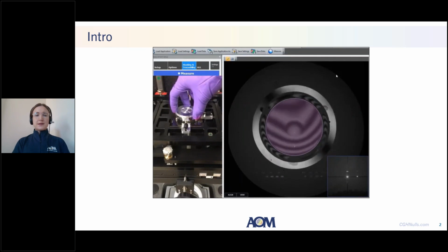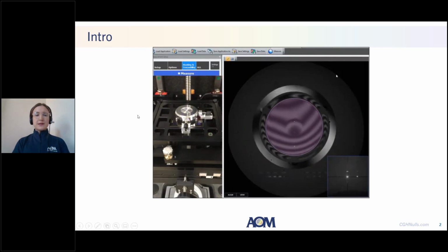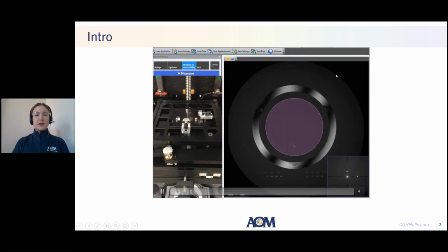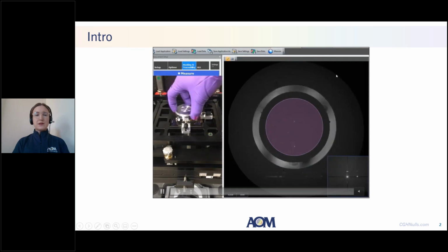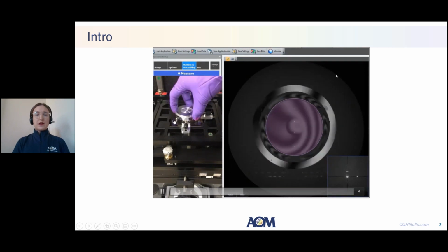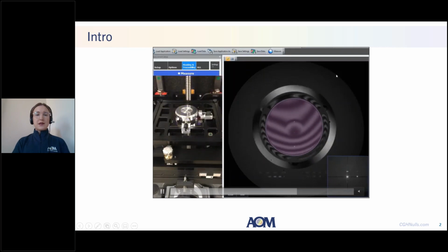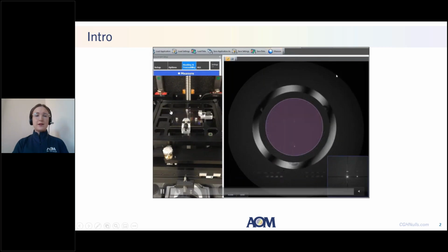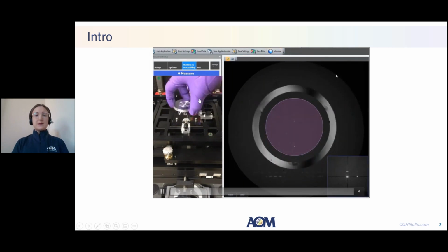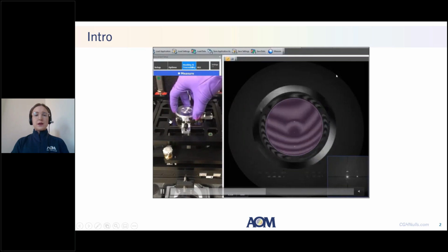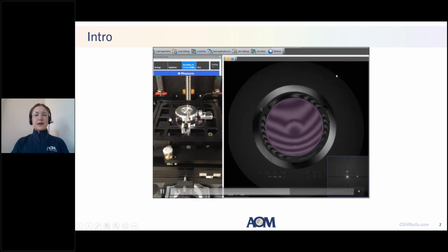And the reason that this is such a quick measurement process is due to consideration of mounting datums on the test optic. In this case, there's a bevel that's diamond turned into it, along with precision located mounting balls that are actually located very precisely with respect to the CGH pattern. And then the test optic is mounted directly against these mounting balls. And so there's actually no alignment needed in this setup.